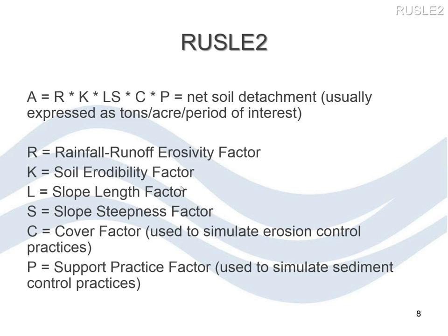Slope length factor is getting at the horizontal length of the slope, so the longer the horizontal slope length, generally the more erosion you have. Slope steepness is usually expressed as percent slope. The steeper the slope, the more erosion you're going to have.